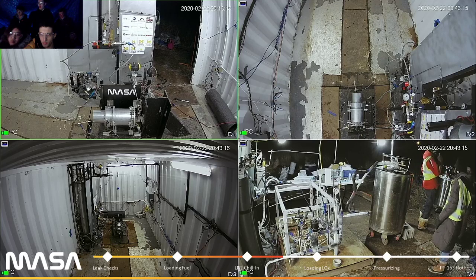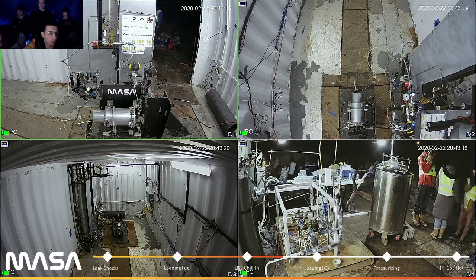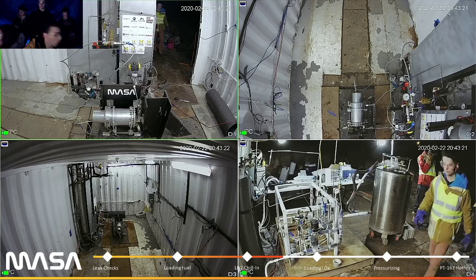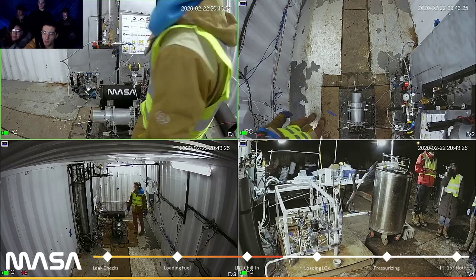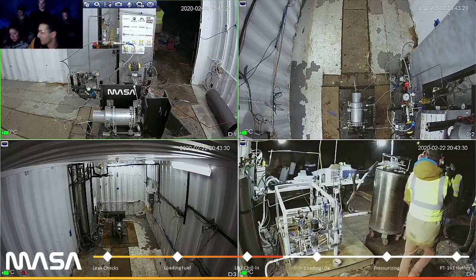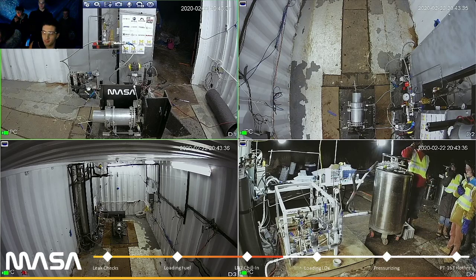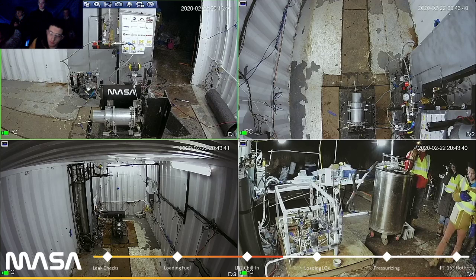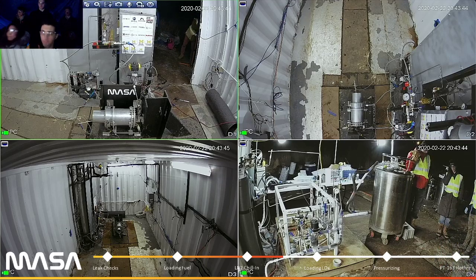And actually, earlier today we did some production of some sheet metal components. We had a water jet cut strip with about 48 holes that we rolled into a ring, and that will be eventually welded down the seam, so you get a continuous ring, and that will be welded on top of our tanks. So that's basically the structural attachment on the top of our tanks. We made a prototype of one of those pieces today, and it turned out pretty well.